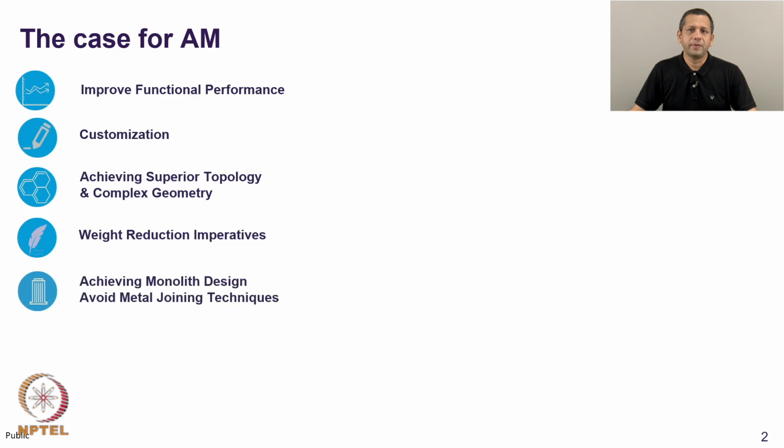Instead of creating separate parts of small sizes of various materials, we can create a monolith structure using additive manufacturing in which different small sections or subparts are made using different materials, and may have different topologies and different internal structures. We do not need to join small parts, so we can avoid joints or welded parts in the large structures.